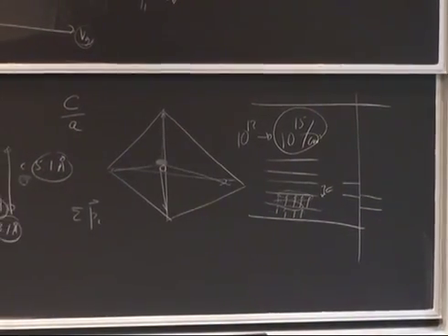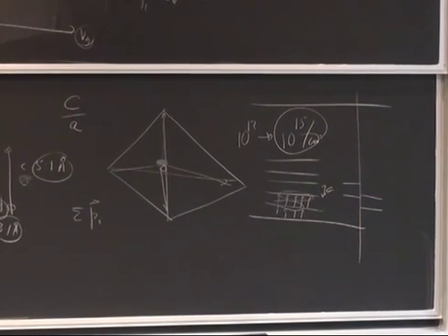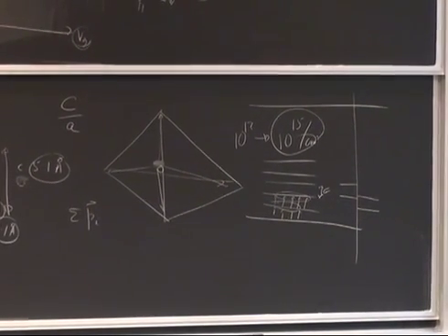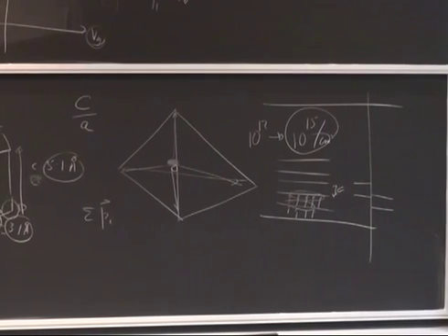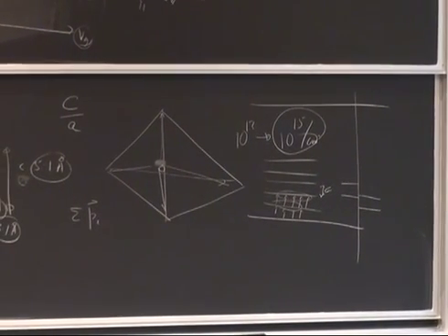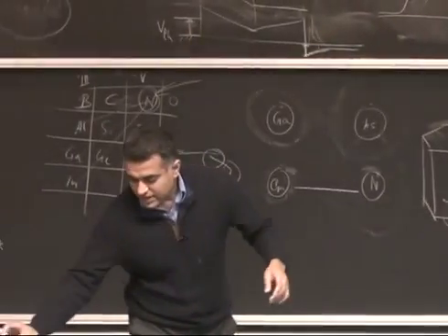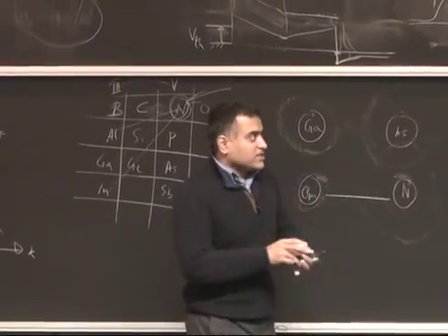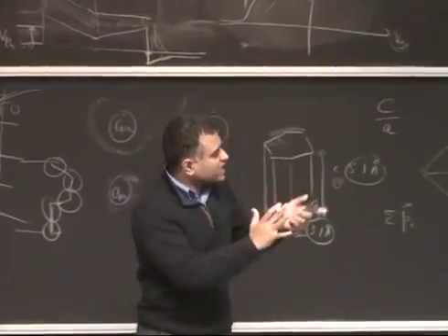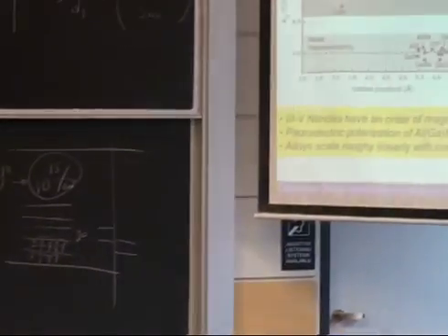But in ferroelectrics, the major difference is you can flip it. You can have domains where some dipoles are this way, some dipoles are that way. In nitrides, they're all in one direction, so you cannot flip it with external fields. So that's the spontaneous polarization, and then when you strain it, you get piezoelectric polarization, and we'll talk about that in the next class. All right. Okay.